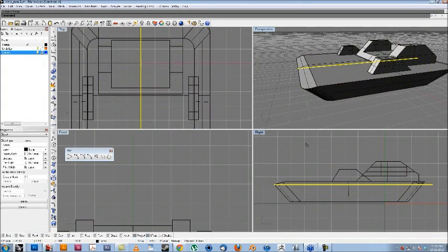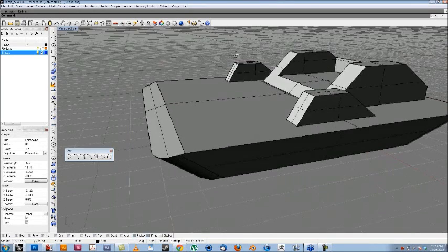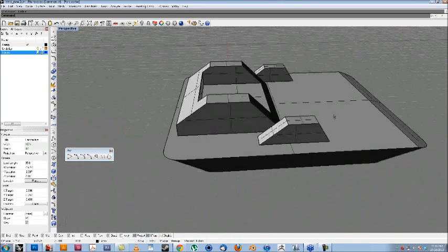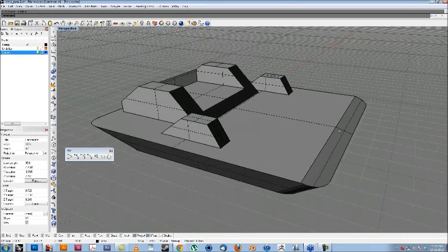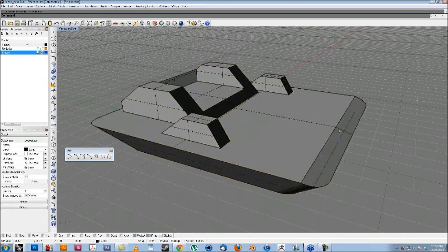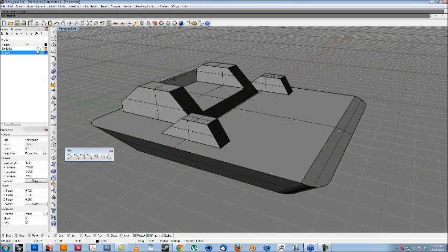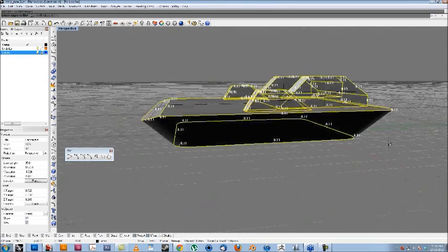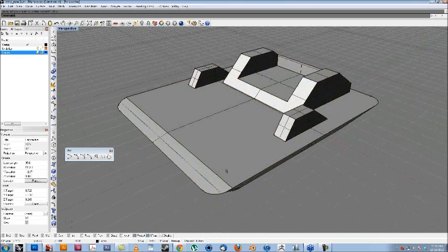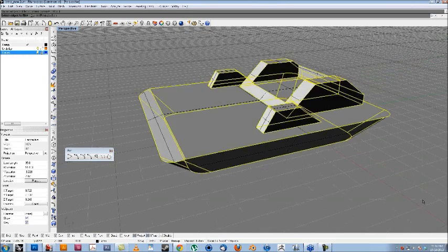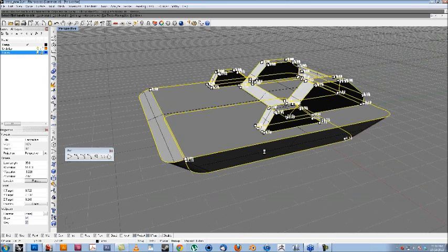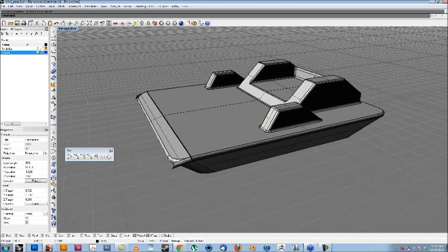I'm wondering, Gabriel, could you remind us what you're doing here right now? Yeah, right now what I'm trying to do is, sometimes when there's a little bit of a surface discontinuity, you get some issues with how the fillets all come together. So what I was trying to do was actually repair the surface so that it wouldn't give me those little tweaks in the geometry. So what I might wind up doing is just going with a smaller radius and seeing if that brings it all together. And it looks like we're still getting some issues.